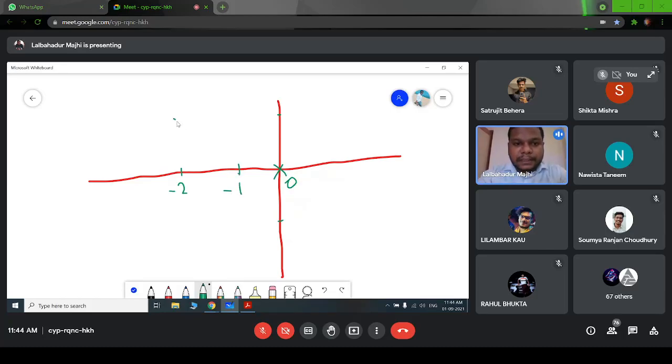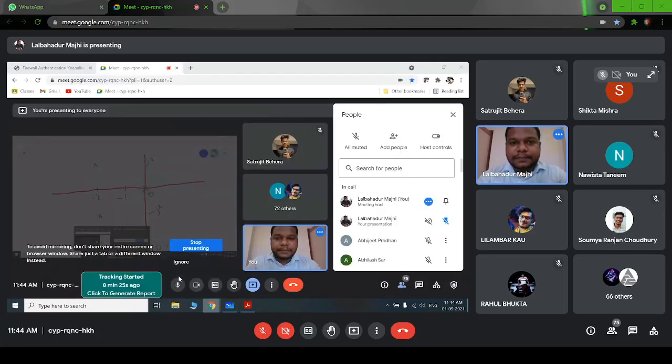So the poles will lie at these points. We have to use graph paper, okay? I am just drawing on simple paper, but you have to use graph paper. So we are getting 3 poles, this is j2 and this is minus j2. Okay, these are our 3 poles. One pole at the origin and the other 2 are the complex conjugate pair of poles.